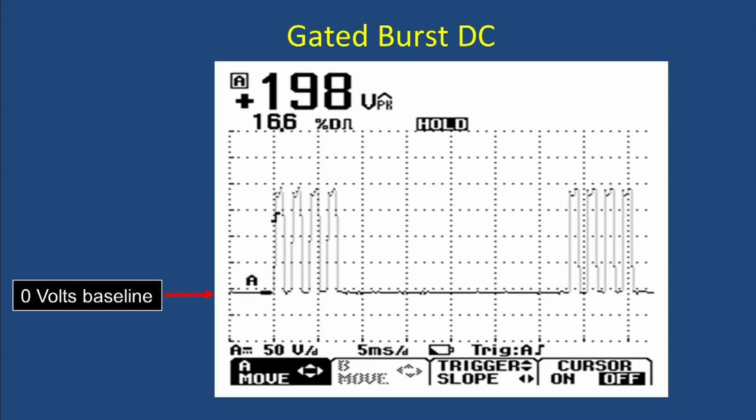This particular waveform was developed because there was real concern about injury to salmon and trout from electrofishing, and there was research to say, well, look, we know that low pulse rates reduce injury potential in salmonids, so let's reduce the pulse rate, but when we do that, they're harder to catch, so let's fool them and have a low pulse rate of packets, and within a packet we'll have these catching high frequency pulses.